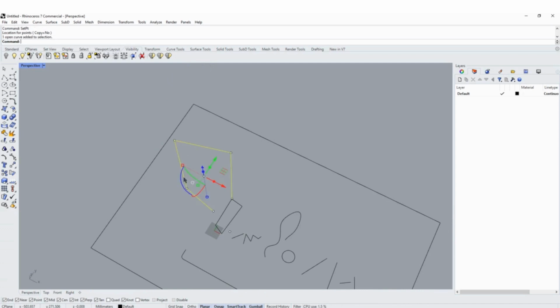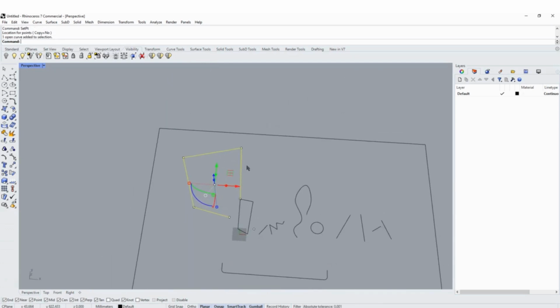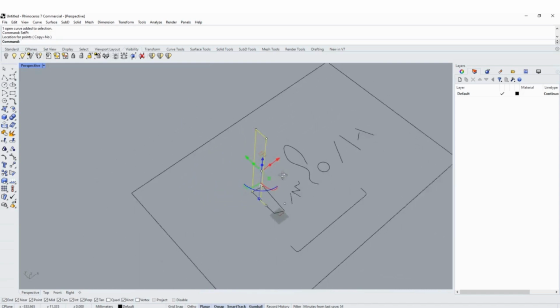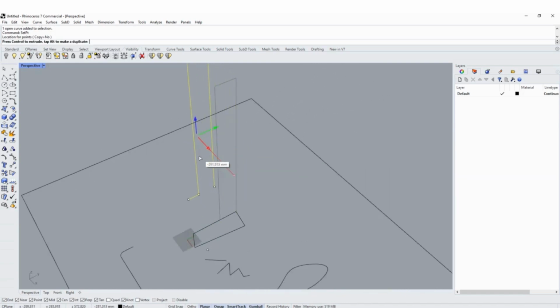The set points function can help further. For example, let's say that I want all these elements to be aligned in the x-axis over here. Let me do set PT again, or press the space bar, because it was the last command that we used. Then I want to select just the X. Let me right click. Right click means just this one, please. Okay, and now it's taking these points of mine and aligning them in the X. So now it's a flattened element.